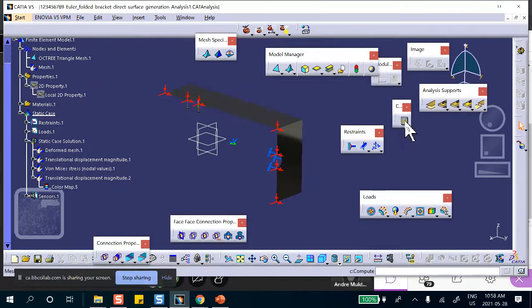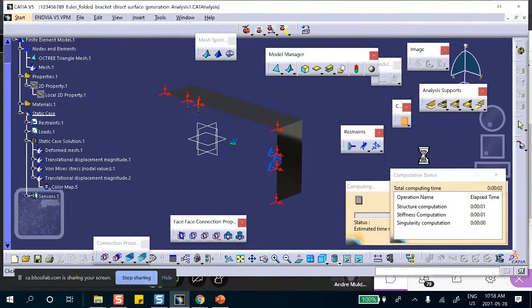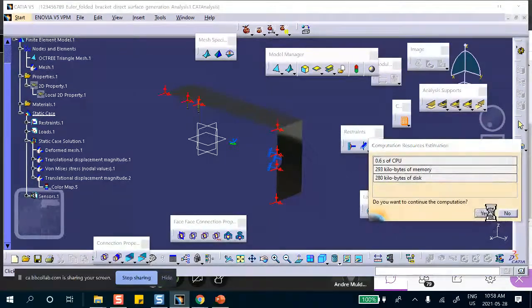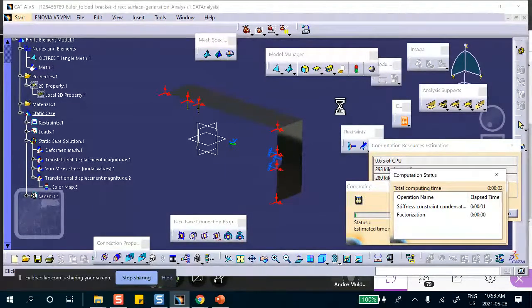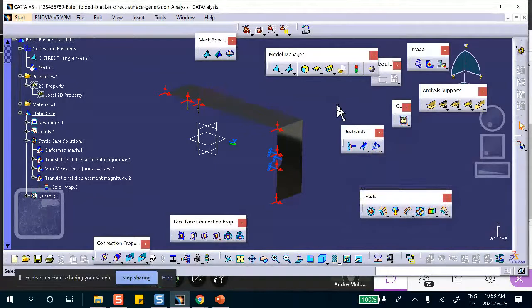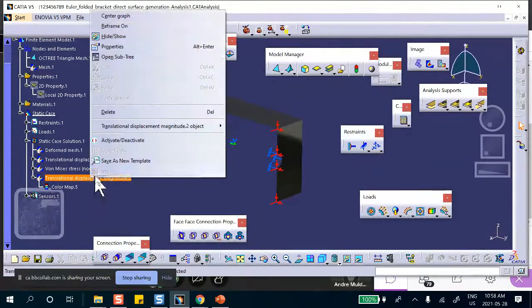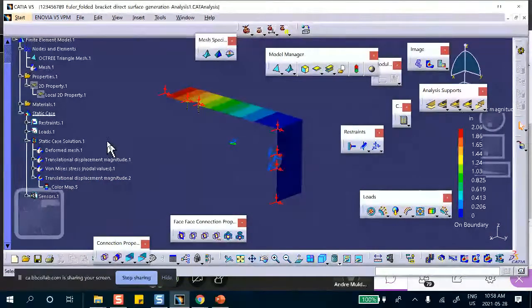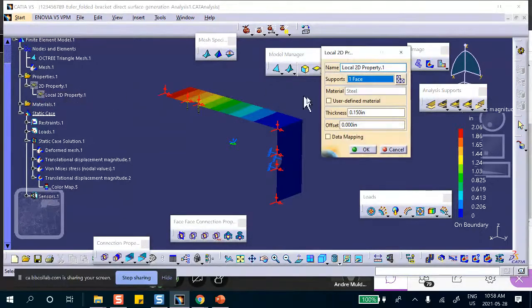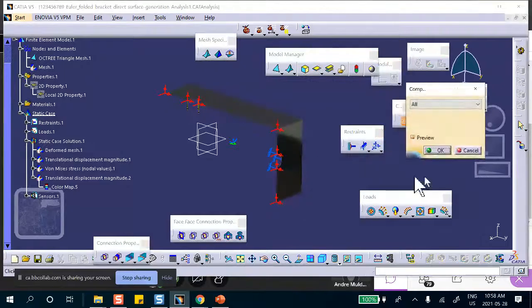I left this thing alone. Excellent. Let's look at the deflection now. 2 inches. That's more reasonable. Or if you make this vertical one, instead of 0.15 inch, 0.2 inches, run it.